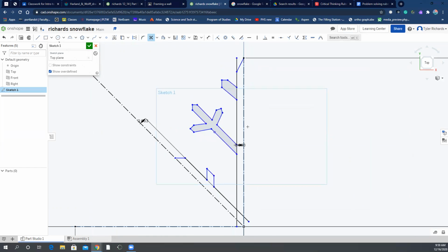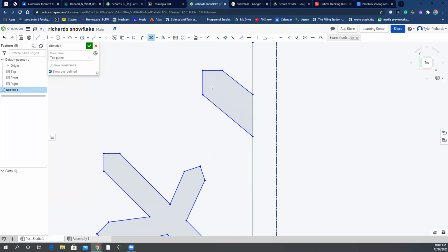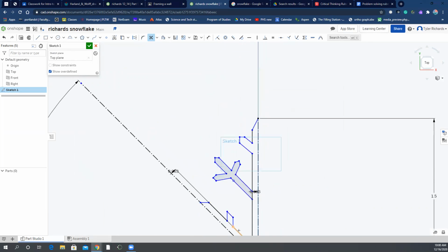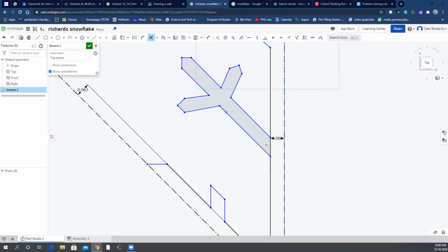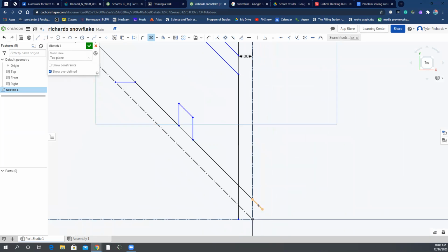And the reason I'm removing these pieces is I'm trying to create one solid shape, okay? So what do I mean by that? Well, let's say my mouse is stuck inside, here, I'll zoom in. Let's say my mouse is inside this box, this shape that we have drawn here. Well, if I want to move my mouse over to this shape, I can't because I'm technically hitting this line here. So I need to get rid of that, right? So that's a quick way you can figure out if you need to remove a line. You can place yourself in a shape, and then if your mouse can't freely move to the next shape, that means you probably have a line that needs to be removed. And so I've got to also get rid of these ones.